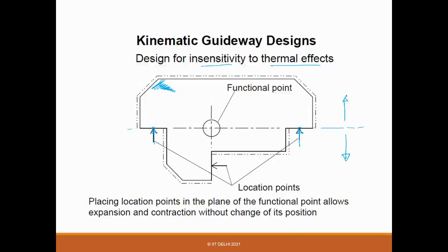So what virtually you have found out is this line is insensitive. Any location on this line is insensitive towards this expansion, right? But it can still have these deformations, because the heat can lead to deformation in all directions. So then you define another contact here. Then you can just define a normal, and along this it will expand, and things will not expand along this one, right?